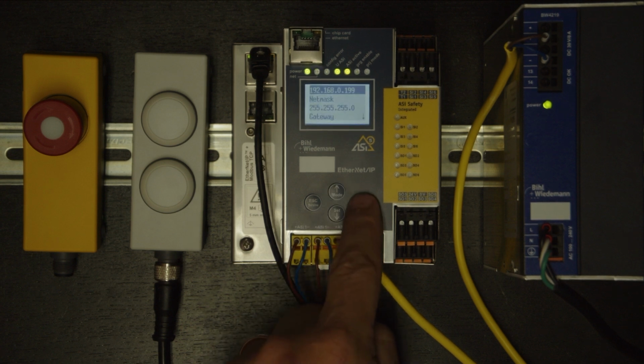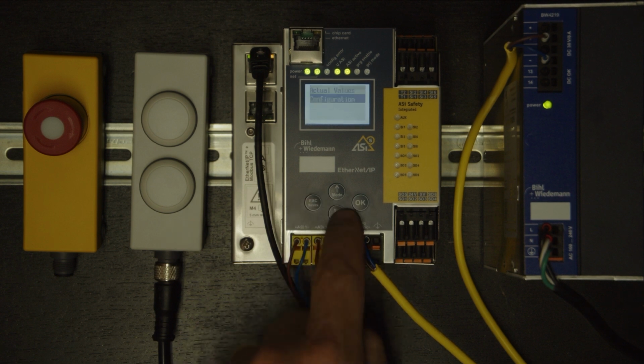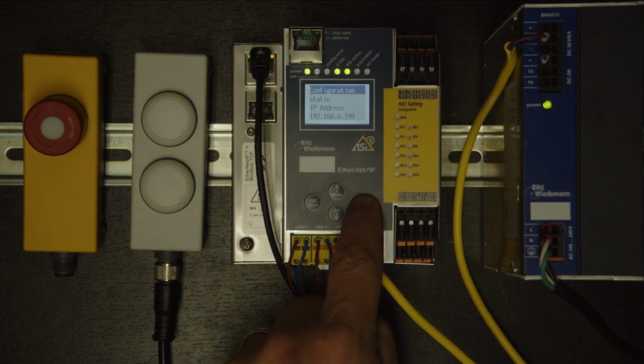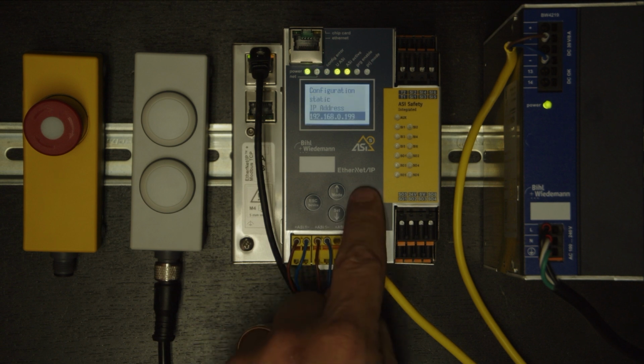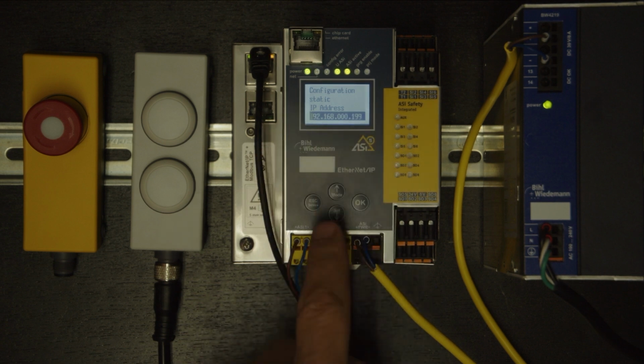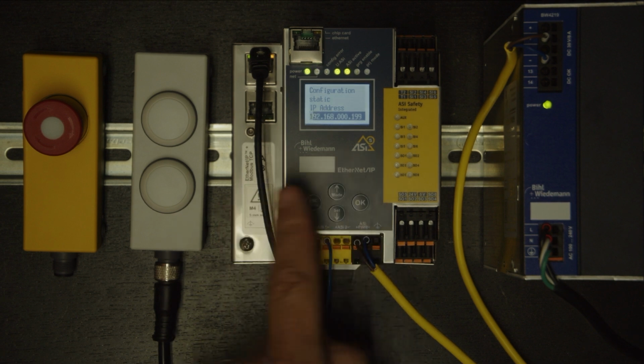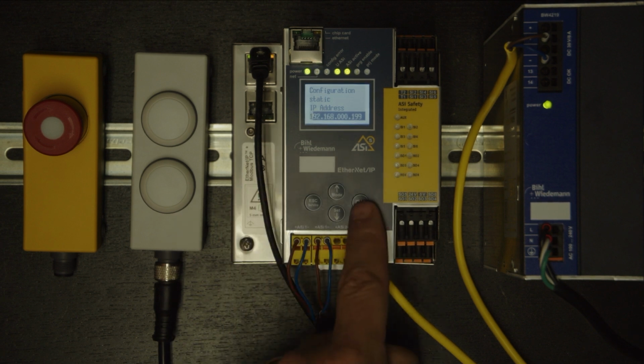Now, when you change this, basically you go to the configuration menu and hit Enter. Once you go down, you want to decide whether this is a DHCP or a static address. I wanted a static address. Then you press Enter, and you have the ability to change the IP address digit by digit using the up and down arrows, and then left and right to navigate from digit to digit. When your cursor gets all the way to the far right and you hit the OK button, then it takes that.